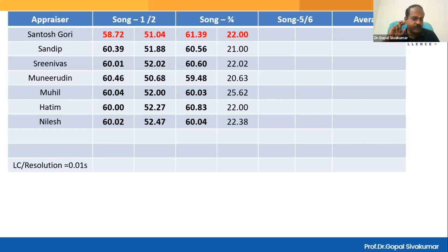As a project leader, as a person who is conducting the gauge study, you should know what percentage of the parts are good and what percentage are bad, mixed together. You can keep it 50-50. You can keep it 60-40. It is up to you. Do you understand the point? First point, what I said, the appraiser should not know the true values. Second point, they should not even know that some of the parts they are measuring repeatedly. Otherwise, there is no need to measure. Please understand.